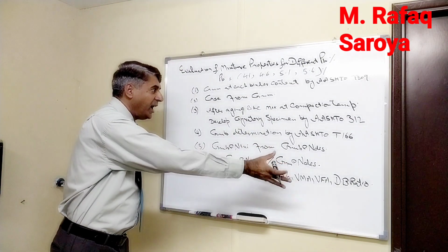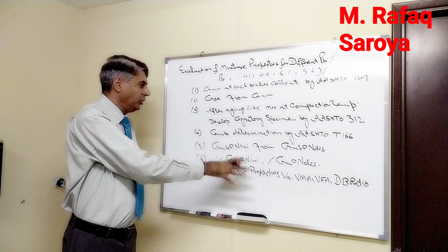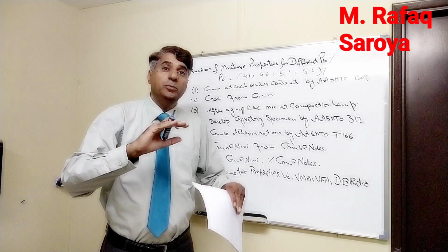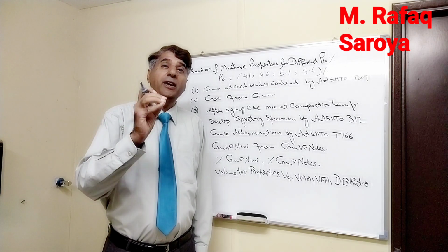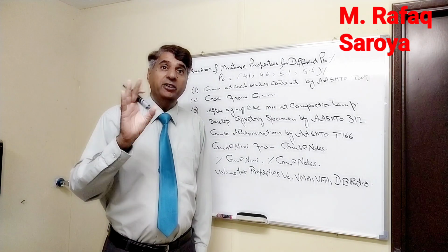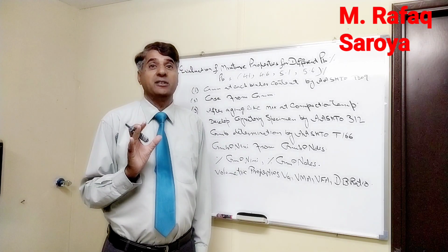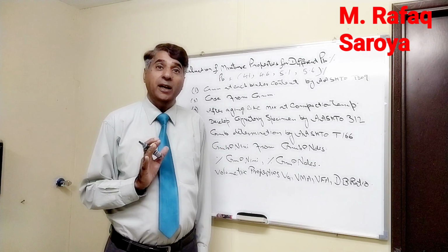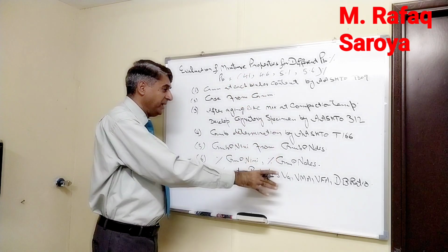When we have done all of this, which I have written over here, then we will try to reach to the conclusion that which design should be considered, at which binder content we are going to get the 4% air voids, and then the other remaining properties will be verified from this. So in my coming video, I will go on explaining this.